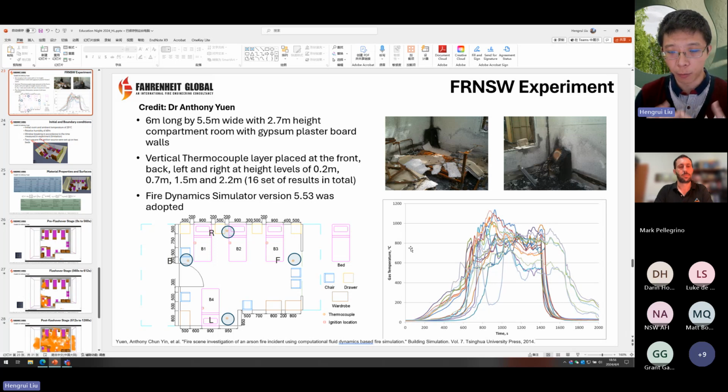If you set up your model very poorly, it's not the correct fire, it's not dense enough or fine enough in the mesh, you cannot capture the fire behavior. There is a risk of your model giving you a very garbage result. A golden word in our simulation guides is garbage in, garbage out. So if your model is not correct, you shouldn't expect your results to be correct.